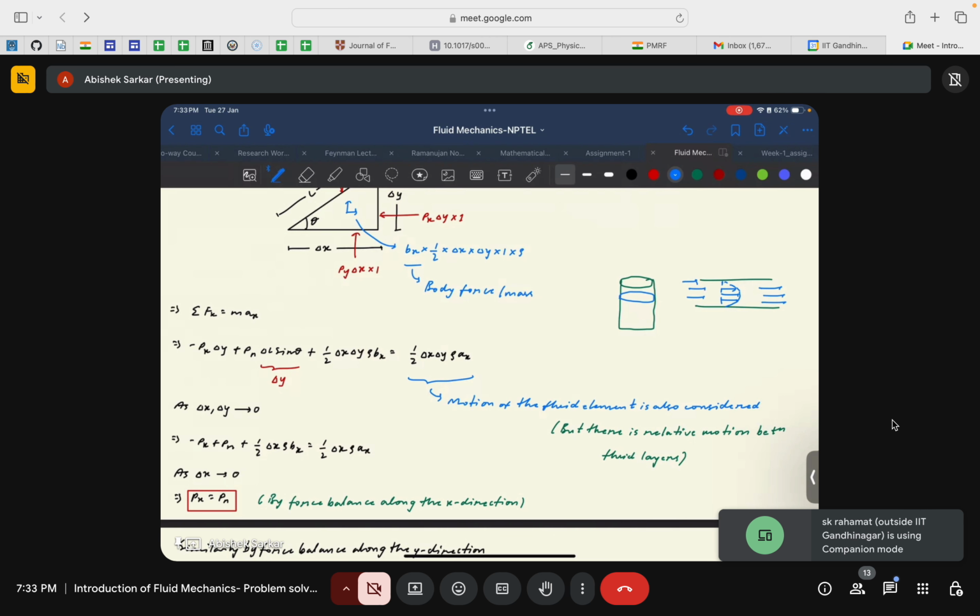So in the case of flow through a pipe, since the fluid is in motion, of course the bulk of fluid moves, but the key differentiating factor is that in this kind of motion there is a relative motion between the layers of fluid that basically gives rise to the velocity profile that we see. If you are not well versed with that, just take it for granted for now: for flow through pipes the fluid will undergo motion where there is a relative motion between the layers of fluid.